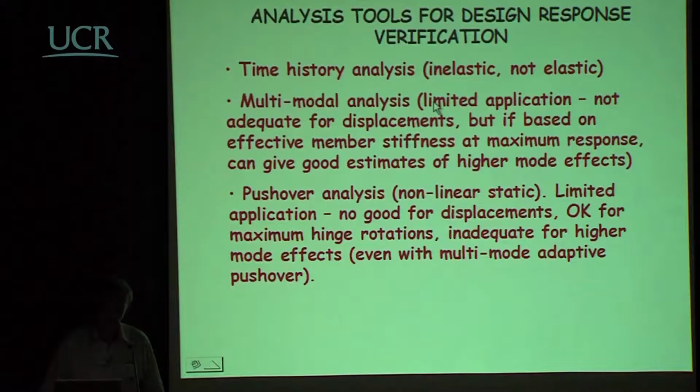Multimodal analysis, I've indicated many times that I'm not very enamored of multimodal analysis. It has limited application. It's not adequate for determining the displacements, but if based on effective member stiffnesses at maximum response, it can give a good estimate of higher mode effects. Pushover analysis is perhaps the other option to the time history analysis, often called nonlinear static analysis. Again, limited application. It's not going to tell you what the displacement demand is. All it's going to do is give you a force displacement response, generally only related to the fundamental inelastic mode.